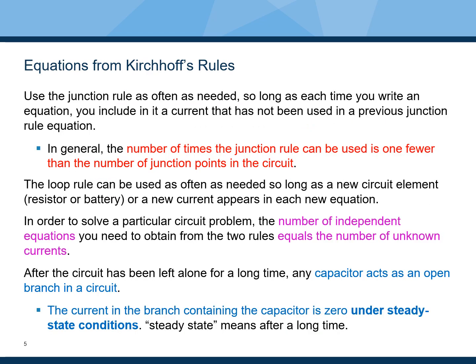Now there's a whole bunch of additional ideas and suggestions given to you. One of the things that I really like is the observation that a capacitor that is uncharged and instantaneously thrown into a circuit basically behaves like a closed circuit. But a capacitor that has been allowed to stay in a circuit for a very long time reaches a steady state where it behaves like an open circuit. We'll see in time when we get to the next unit why this rule is particularly meaningful.